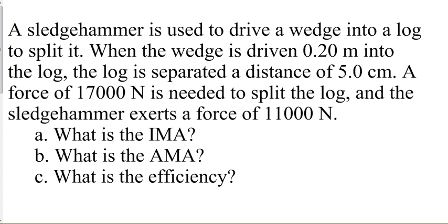A sledgehammer is used to drive a wedge into a log to split it. When the wedge is driven 0.20 meters into the log, it is separated a distance of 5.0 centimeters. A force of 17,000 newtons is needed to split the log, and the sledgehammer exerts a force of 11,000 newtons. What is the IMA? And so for this, we need to think back to the equation. IMA is a ratio of the distances, the dE over dr.